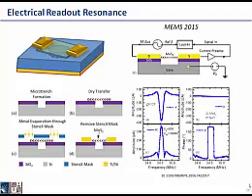So here's the fabrication process. To keep the molybdenum disulfide flake really clean, we basically start with a prefabricated micro trench, and we transfer the atomic crystal layer directly onto it. Then, instead of using lithography, we use a contact mask such that we don't need to put any resist on the device, and evaporate directly through the mask to put contact on it. This way, we can prevent the atomic flake from collapsing during the wet processing.